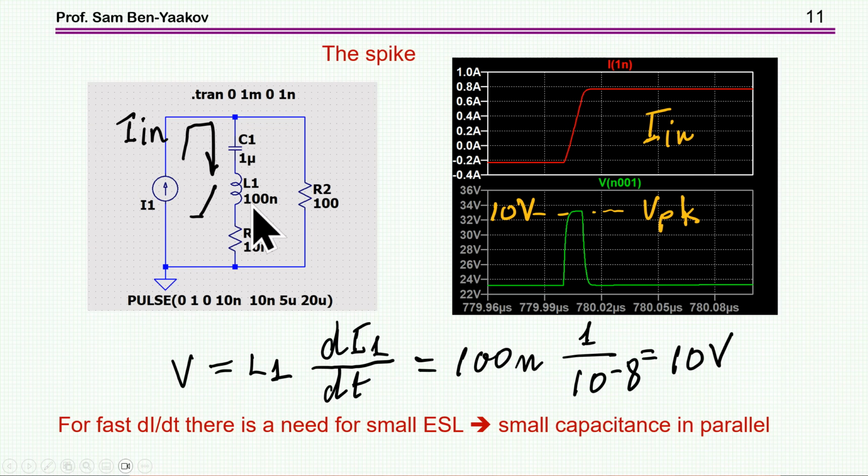the inductance is a function of the structure. The smaller the capacitor, supposedly, the smaller the inductance will be. So this is where this idea of putting a 0.1 microfarad capacitor is coming from. The capacitance doesn't matter that much. During this transition, you have very high frequencies, so 0.1 microfarad is okay, but a smaller capacitor will hopefully have a lower inductance because it is smaller. So let's have a look at what the reality is.